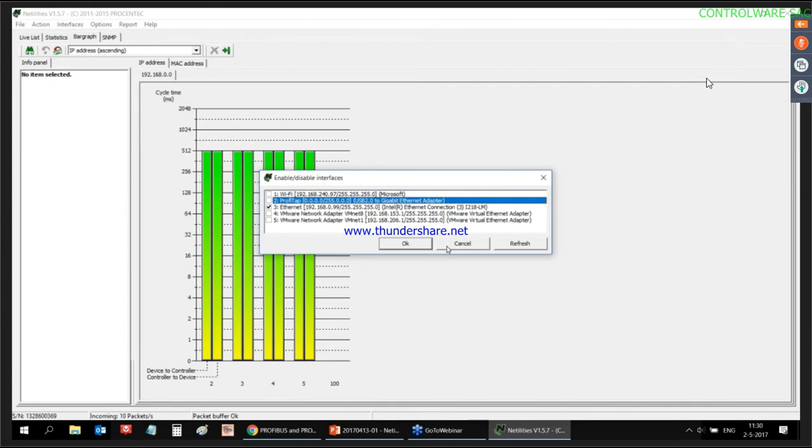not sending continuously messages to your devices, like broadcast, trying to connect over the network, try to set up a connection, try DHCP requests, etc. So it's not mandatory. We usually don't do that all the time. But if you see a Wireshark trace with a Profinet setup with a set IP address and without a set IP address, there is a difference. There are a lot fewer Windows messages when you set the IP address.